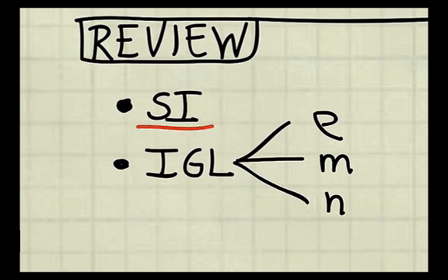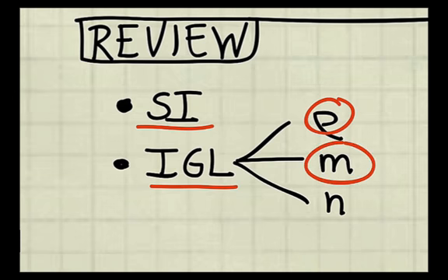Use SI whenever you can. Saves time, eliminates mistakes. Remember, the ideal gas law has 3 forms: the density form, the mass form, and the mole form. Use whichever form is easiest on a given problem.